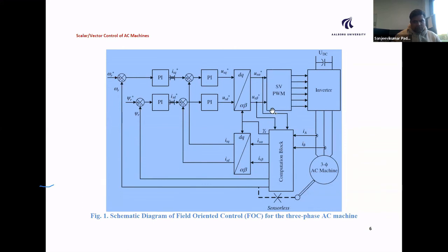The space vector modulation is carried out, and all the 6 PWMs which are required for the inverter are given, so that I can drive the inverter for the required speed control of the motor, which is driven by the inverter. Whatever speed I give, whatever flux I give, the motor will run at that same value.